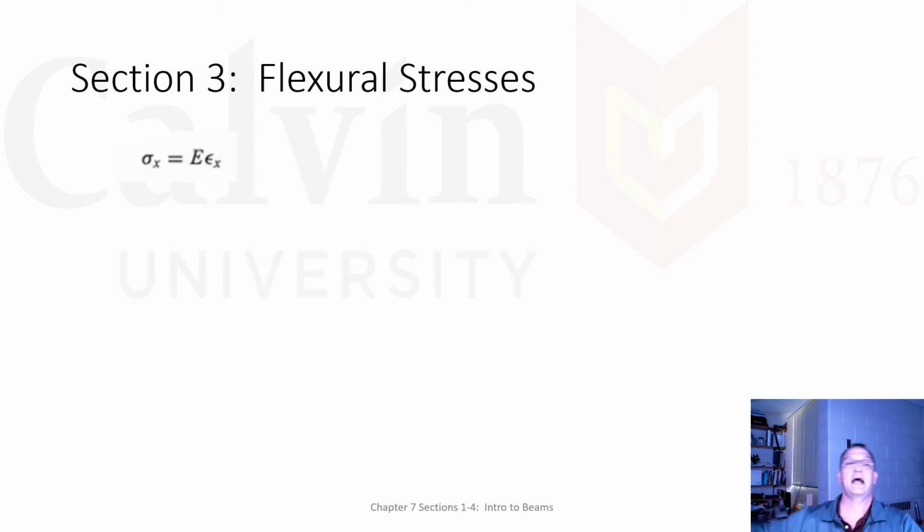We're going to take that forward to calculate our flexural stresses. And we do that going right back to our definition of Young's modulus. We've rearranged it. Now, because we're trying to solve for stresses, we know the material property, and we've got an equation for strain, so we can make the next step.